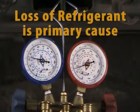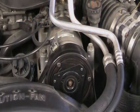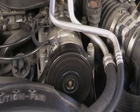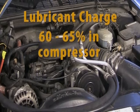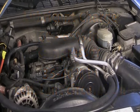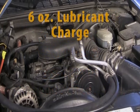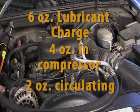Loss of refrigerant is the primary cause of most compressor failures, since the refrigerant is responsible for carrying the lubricant that comes out of the compressor through the system and returning it back to the compressor. A properly operating system will have 60 to 65% of its lubricant charge in the compressor at all times, while the remaining 35 to 40% is in constant circulation. Therefore, a typical system with 6 ounces of lubricant should have 4 ounces in the compressor and 2 ounces circulating.